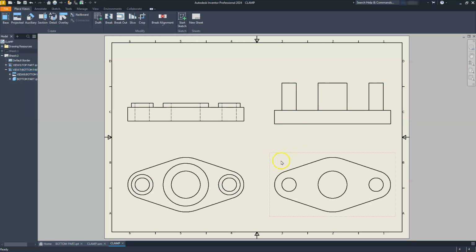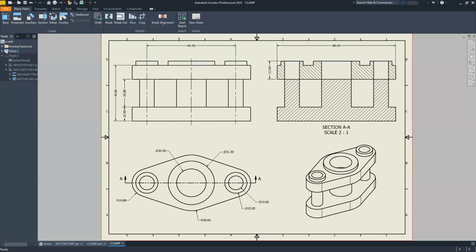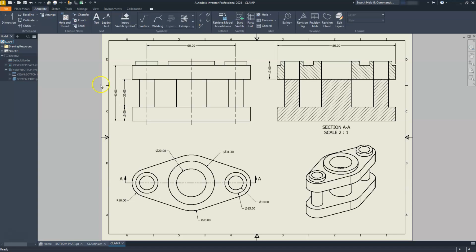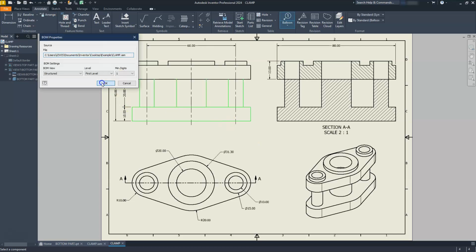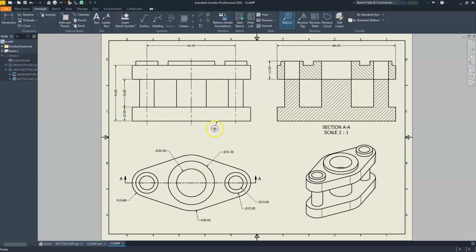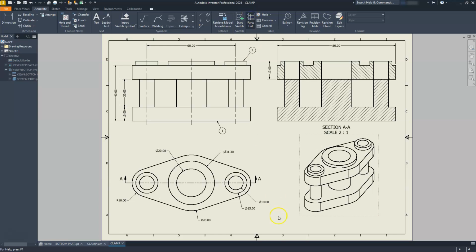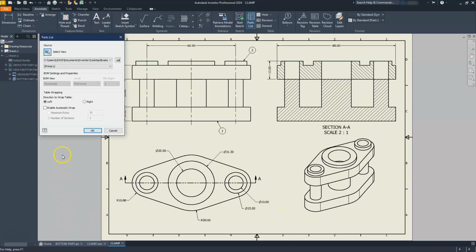But anyway, you kind of see what I've done here, right? So I can go through and put dimensions on these and make them individuals and create a parts list and things of that nature. And yes, this does have parts lists, kind of like what we did in AutoCAD, in that we can label stuff with balloons, right? So I can tell it here, and it's asking me right now, I don't have any of my parts list created, but I can go ahead and label these as so. Let's go ahead and move this up a little bit, just so you see that I can put a parts list on here, and it should be a fairly small parts list.